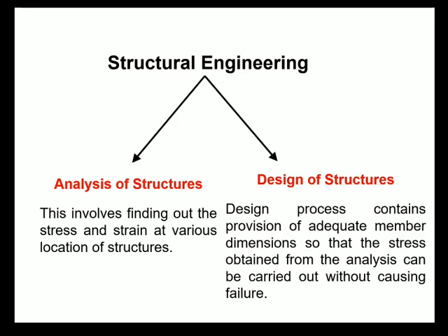Let us try to understand the two terms we normally hear very frequently, analysis and design. Let us first understand the difference between analysis and design. Analysis means finding, for a given loading condition, the maximum stresses and strains which are being generated at each and every point of each member of the structure. That means knowing the stress and strain distribution throughout the structure. That is the objective of carrying out analysis.